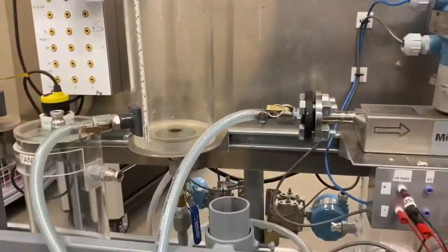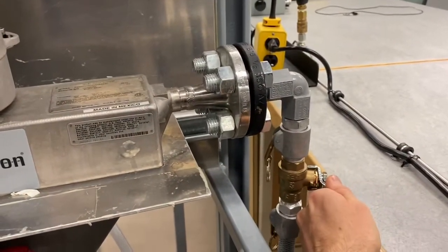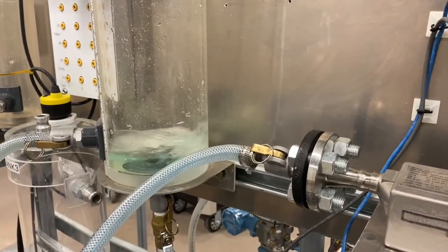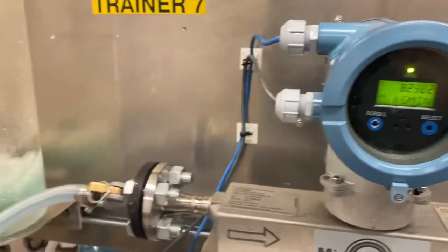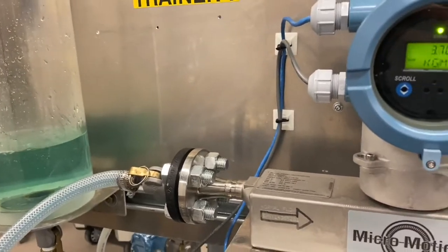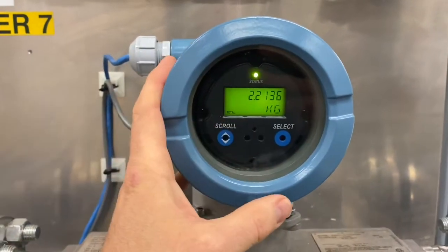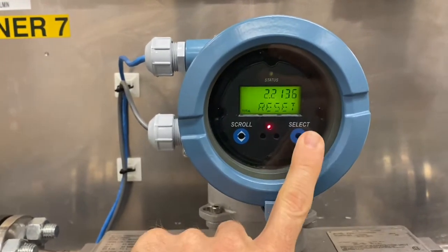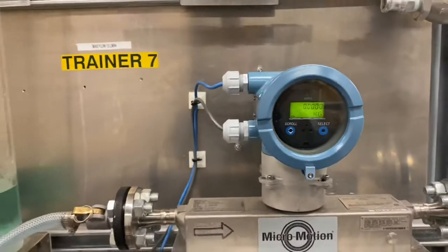All right, so I have the pump turned on here. I've got the valve on the bottom of the tank open. I'm just going to slowly open our valve on the downstream side of the Coriolis meter and just start filling up the vessel. And you can see we're reading mass flow right there. And just shut the valve on the bottom of the tank here, let that fill up a little bit, and then we'll shut this. And we should see this flow right there, it dropped right to 0, which is good. And we'll probably now have a mass value there. I'm just going to reset that. There, it's reset. You can exit. So now we're ready to do our first proof.